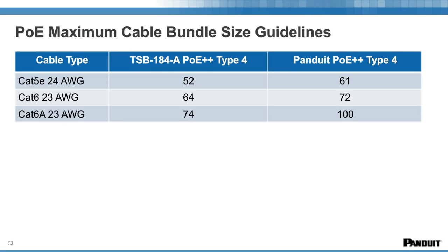So again, cable bundling, both for 2.5 and 5 gig and PoE, is going to be an additional focus point for end users and installers going forward that they typically didn't really have to worry about in the past. And I think many people really enjoyed, and Patrick's website has done a great job posting, pictures of very beautiful cable management of all these tightly bundled cables and how fantastic they look. Well, from a performance standpoint, when you get into high power PoE and 2.5 and 5 gig, there's some potential concern with that tightly bundled cable all the way from source to end device.